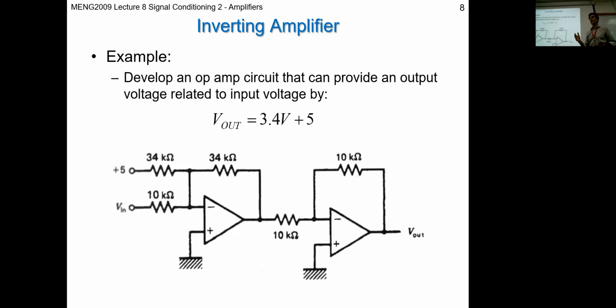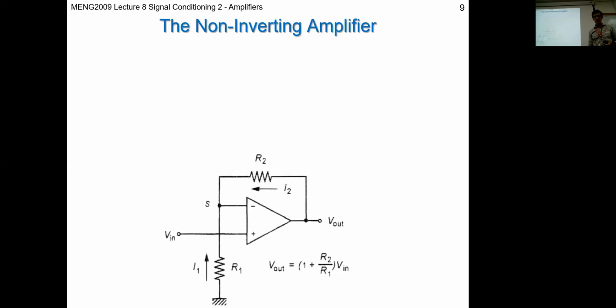You're going to need 2 things. You're going to need a gain on your signal to give you the right relationship between the range of values of the sensor, which is 3 to 7 millivolts, to 0 to 5. So you need that gain, but you also need an offset because you have to correct for the fact that 0 is 3. So you need a negative voltage to pull down. That's where this constant value offset will come in. So you can actually do it with a circuit just like this. You just have to change the values to get it into something that could work.